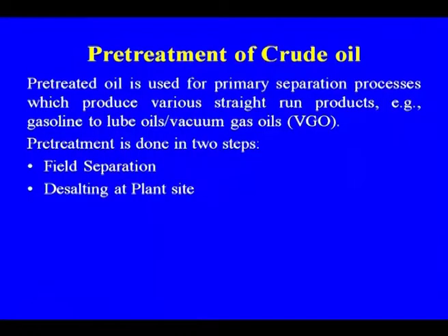So, field separation and desalting at the plant site, because the requirement is very stringent in case of the presence of salt in the crude oil. And so, desalting, all the refineries perform it at the site, that means in the refinery.